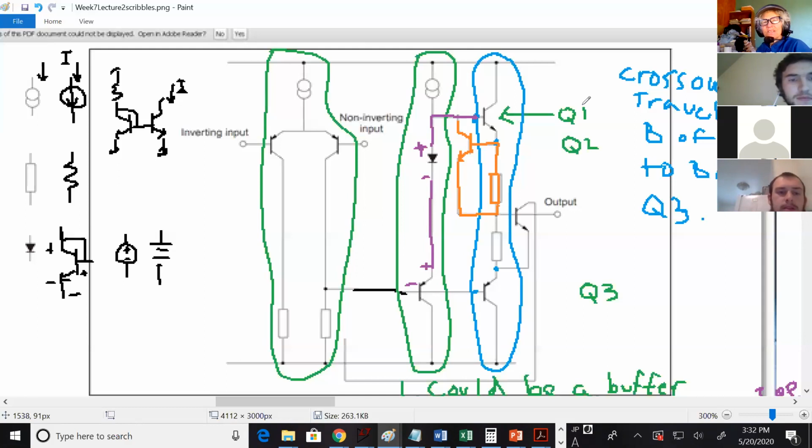So I agree. If there's too much current through the push-pull, then what happens to the voltage across the resistor? You already said it. It would go up. So now you have a bigger voltage across that resistor. What's that do to Q2? Does it turn it on?